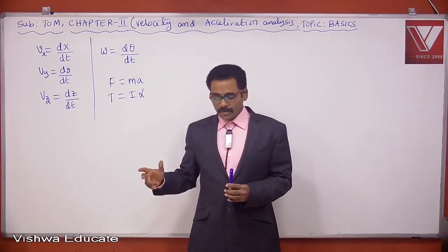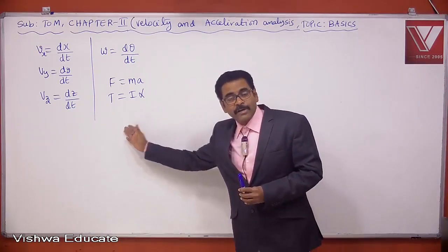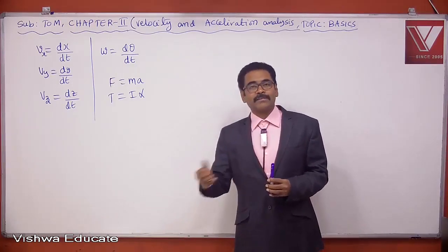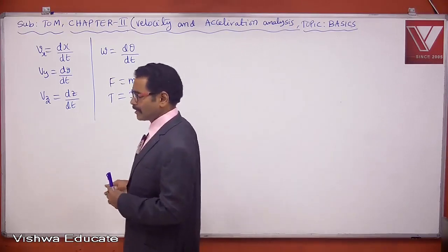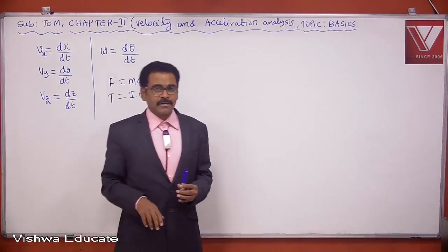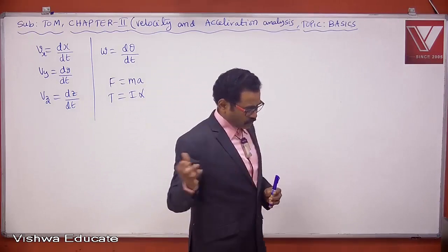For performing balancing, first you have to perform vibrational analysis. If there is no vibration, you need not balance that machine. No vibration means no unbalanced force and no unbalanced couple.